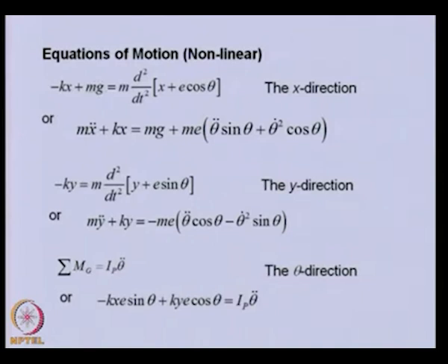So, for derivation of the equation of motion, x will be vertical and y is horizontal, so because of that this is negative, otherwise there is no problem in the sign. So, this is the equation of motion. Basically, you can see this is the weight, and as we have seen in the previous lectures also, this is the position of the center of gravity of the rotor, and this is the linear acceleration. If we differentiate this, differentiation of this will give us two components like this. Here e is constant, not variable, but this will give two components once we differentiate twice.